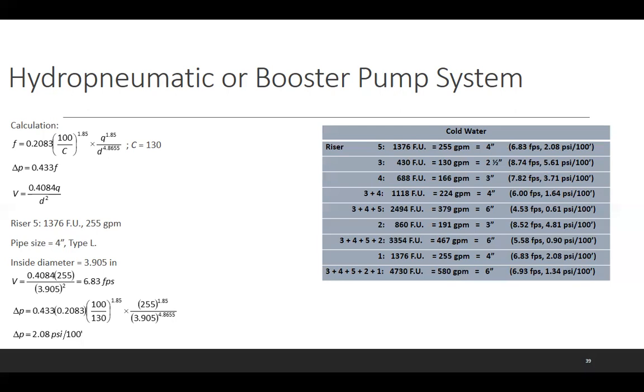Pag masyadong malayo, so that is 8 feet per second ka na. Okay. Or depende sa boss mo, sa authority. The maximum is 8 ka lang. So dito, sa example natin is allowed mag-over ng konti kasi sayang naman, konti lang sa calculation mo 3.2 ginawa mong 4 inches diba? Kung compute mong inside diameter is 3.2, so pwede doon ka na sa 3 inches.